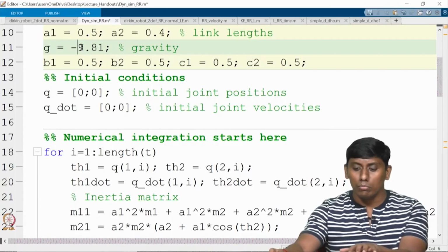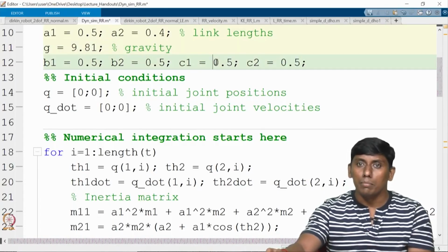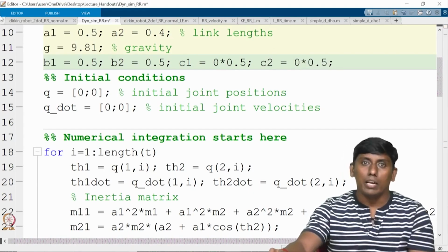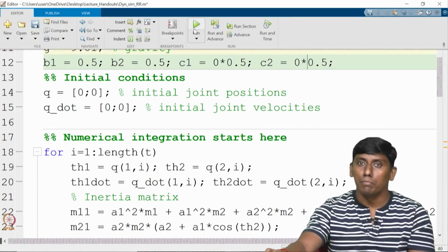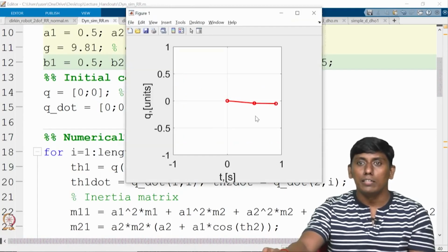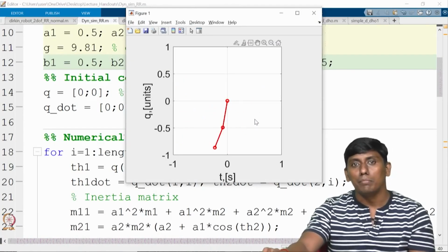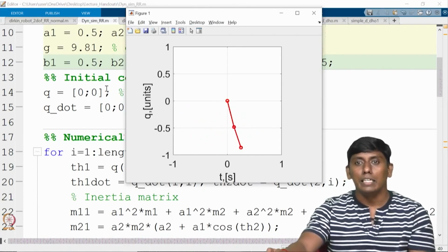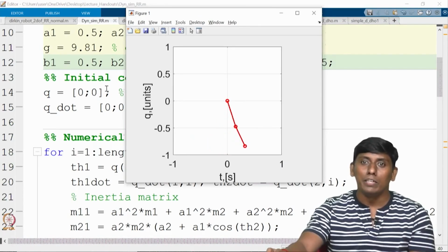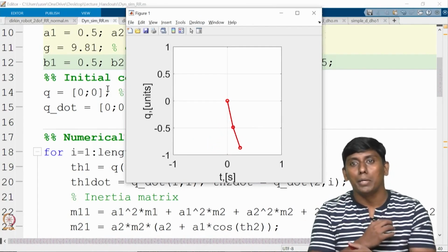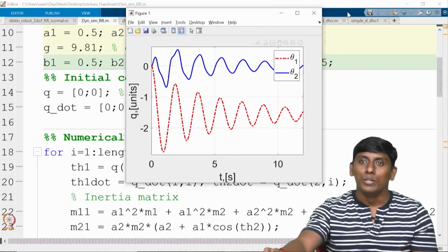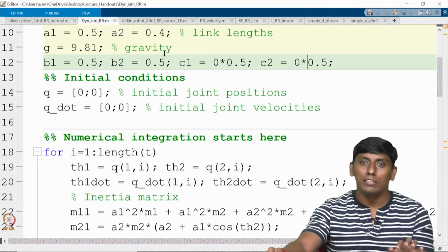So now I assume both Coulomb frictions are 0. Okay. I am checking it with gravity pulling down. Now you can see that it is taking further time. Even the 20 seconds, or whatever duration I gave, is not sufficient to get settled. You can see, right? Now if I eliminate the friction, you will see a completely different phenomenon. It will get some kind of startup energy. It is supposed to be marginally stable, right?